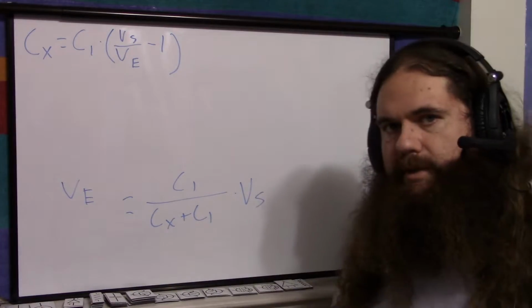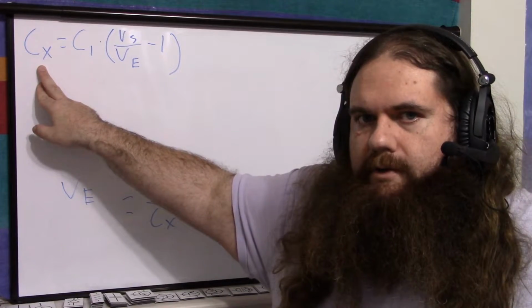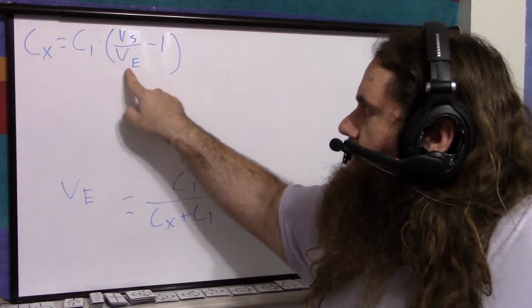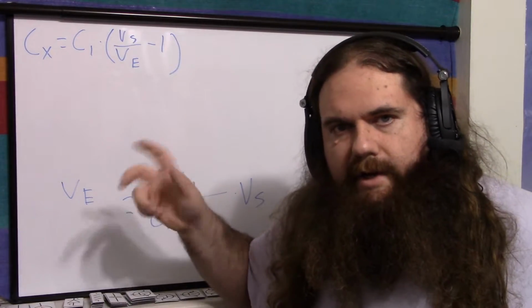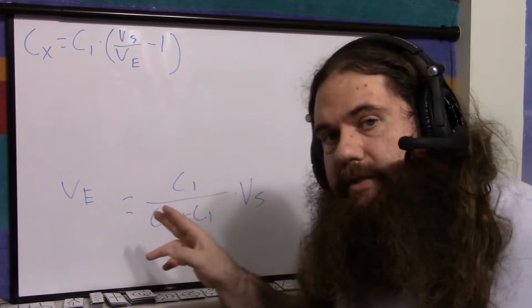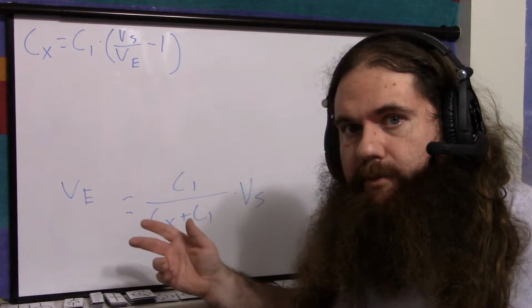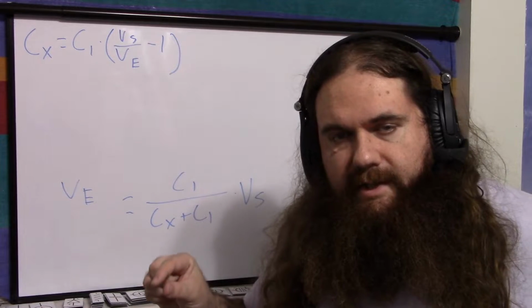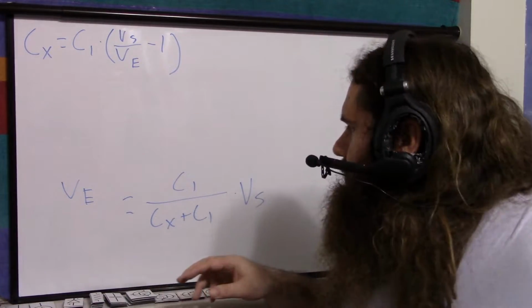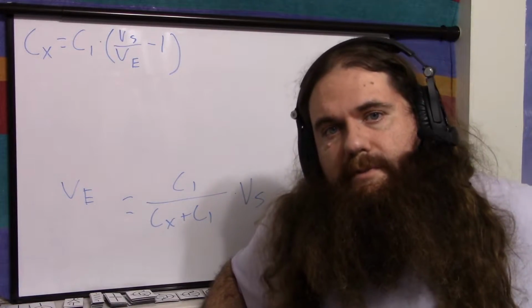So these are the two formulas we use. If we're trying to find an unknown capacitance, we do this and measure the equalized voltage. And if we're testing to see how accurate everything is, maybe we're testing the variances of the capacitors to see just how good or bad it is, then we know the capacitances based on what it says on the little flap, what they should be, and then we find what the voltage should be when we measure.